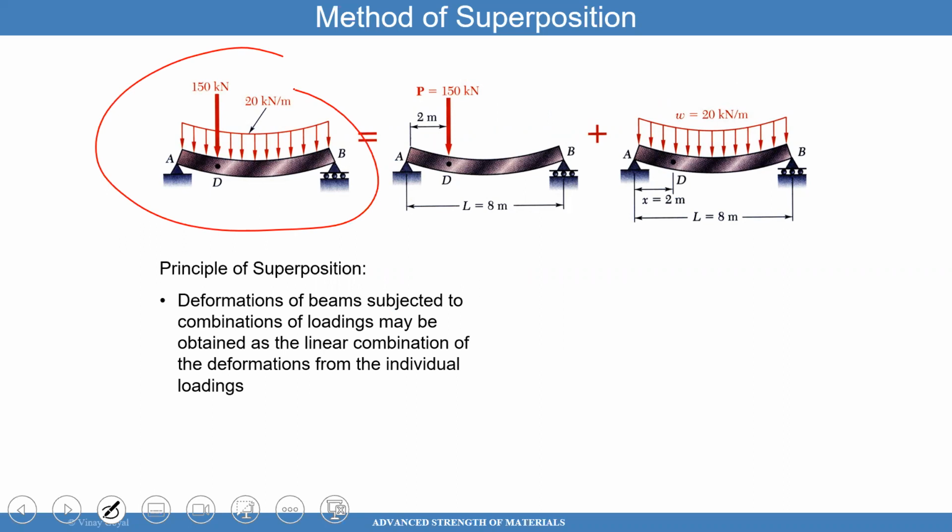But rather than looking at that problem as a whole, what I want to do is break it up into two. I can solve this problem first and then solve this problem separately and then add them up. You will agree with me that solving problem number one and number two should be very feasible, because I did it in the previous examples. So all you have to do is add the solutions up and you can get the deflection of the beam due to that superposition.